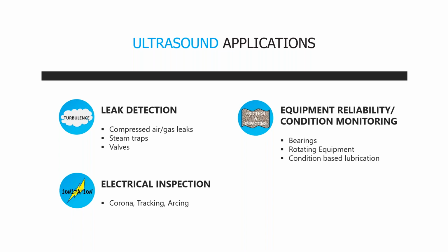And then you can have internal turbulence, say across a steam trap. So if we're listening to a steam trap and that trap cycles open and releases condensate, that creates turbulence. So we actually hear when the steam trap opens, and then we're going to hear when it shuts back, if it's a trap that is designed to cycle that way. Same with a valve. If we're listening to a valve and the valve is supposed to be closed, we're going to be able to tell if there is turbulence across the seat of that valve, where you have flow being restricted through a smaller orifice on the outlet side of that valve. That's going to create turbulence. So we'll be able to tell if that valve is leaking by or not.